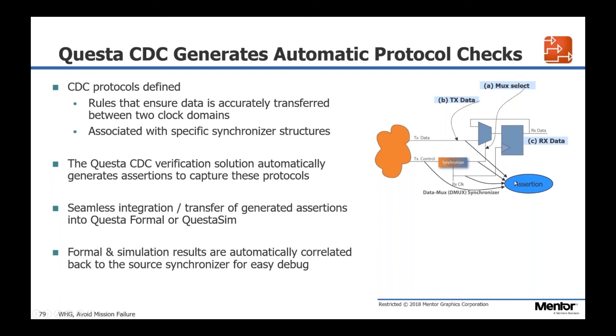But this has a timing protocol which must be obeyed, and that is you better hold this static for the entire time it takes to generate this sample, and for that sample to get synchronized over into this domain, and then turn the sampling off. This signal better not change for that entire amount of time. And so that is the protocol checking that it does.